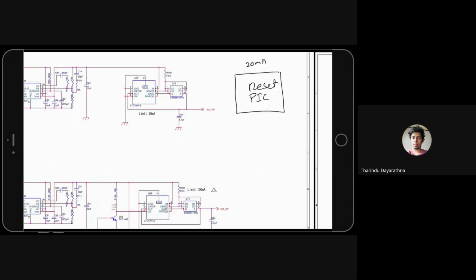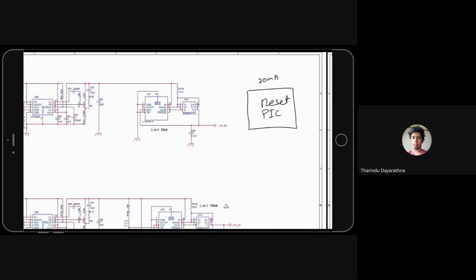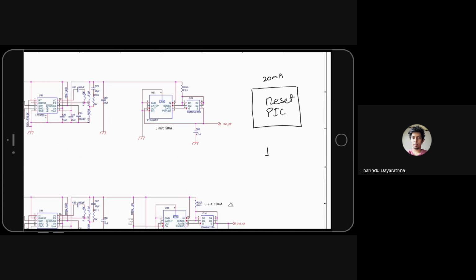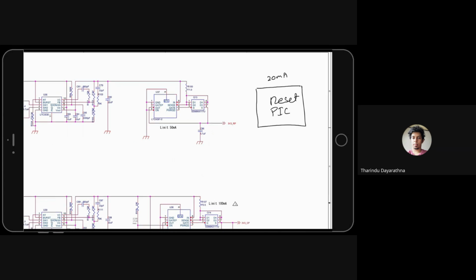But have you heard something called single event latch-up? Single event latch-up is when protons and those things hit the ICs, internal gates, transistors turn on automatically. At that time, a huge current will go through the IC microprocessors. It will be like 200 milliampere, 500 milliampere, or something. That's huge for an IC because the nominal current is 20 milliampere.